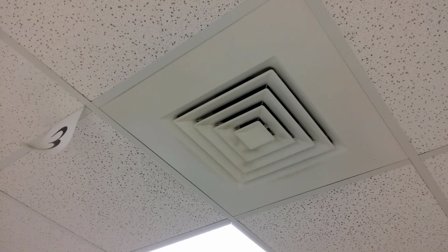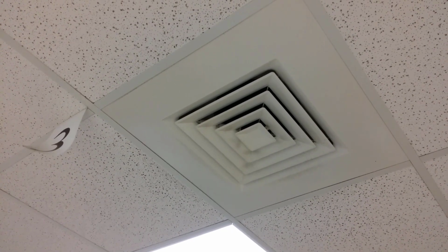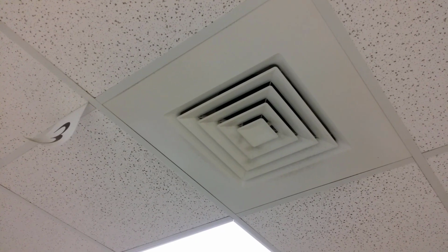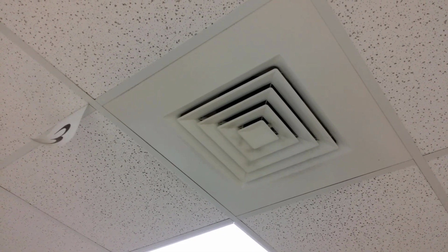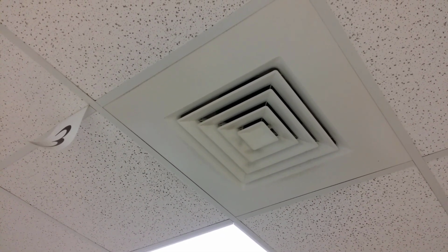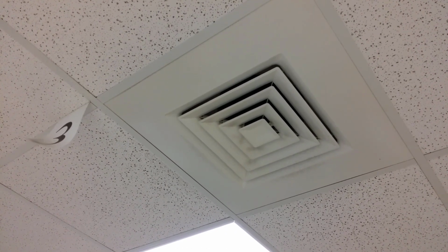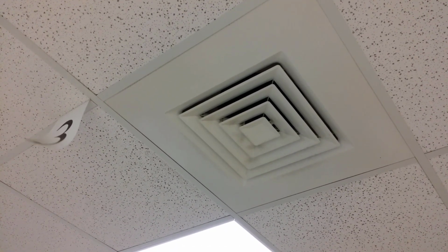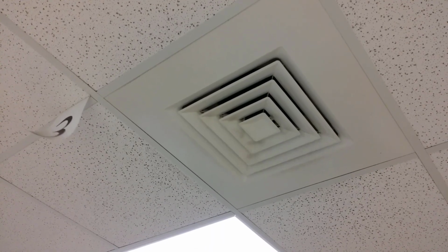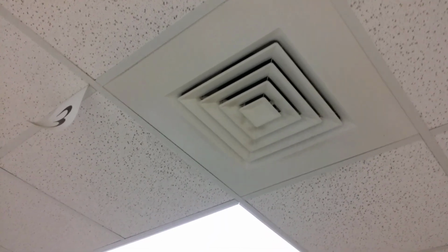In your room, you should also find two features that are probably on your ceiling. One delivers fresh, conditioned air to your room. It is called a supply air vent. Often, it is just called a diffuser because the baffles on its surface help to evenly distribute or diffuse the fresh, conditioned air in a building space.